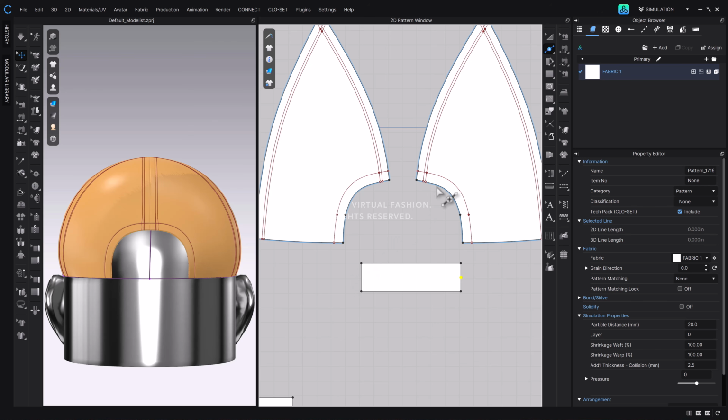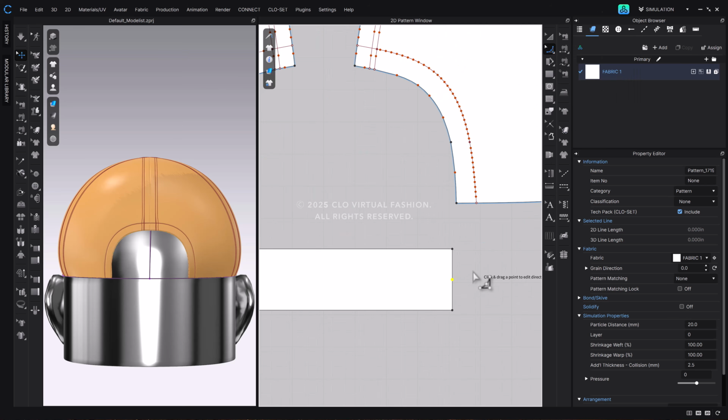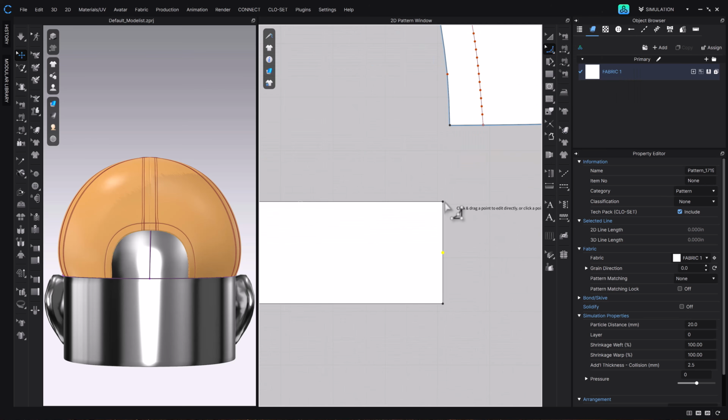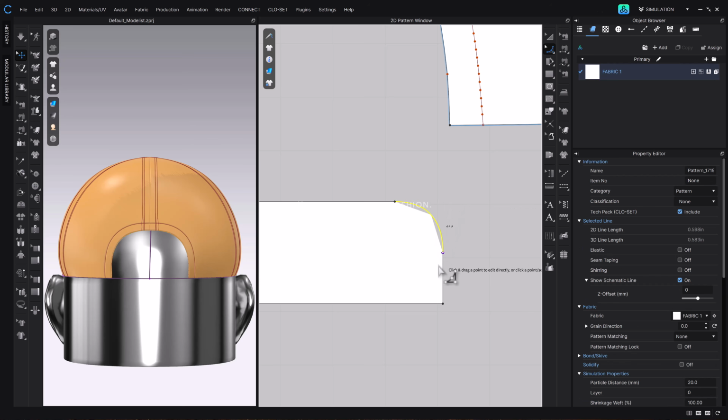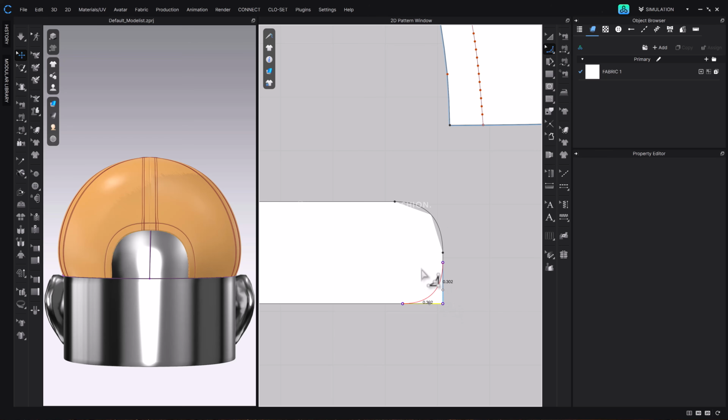After adding the points, press and hold the Edit Pattern tool again, this time selecting the Smooth Curve tool. Click and drag the segment points on the corners to round them out. Round both corners smoothly, adjusting up to the center points.